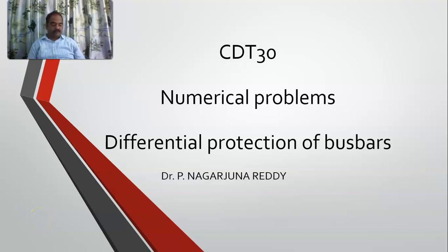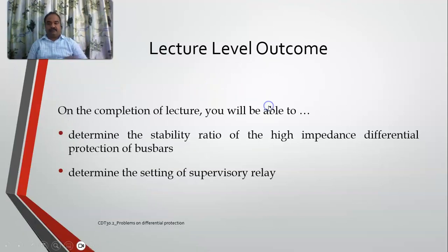Good morning. Today we'll discuss the numerical problems on differential protection of busbars. So far, we have seen the differential protection of busbars, why it is generally employed. Normally, in busbars, we do experience internal faults and also external faults, but the differential protection is employed exclusively for detecting internal faults.